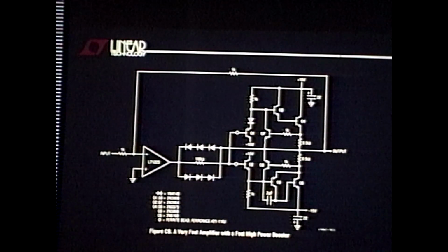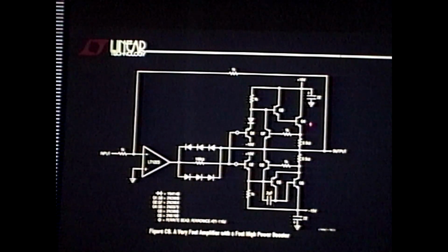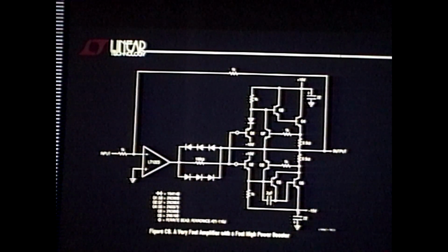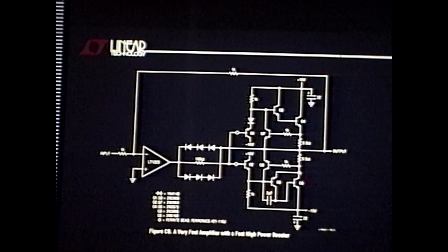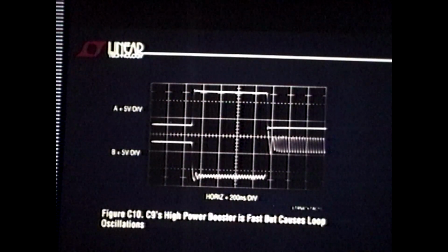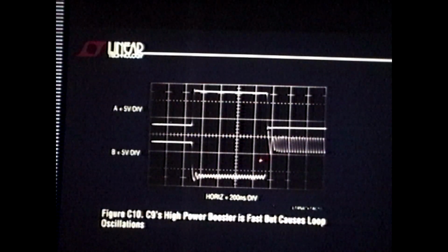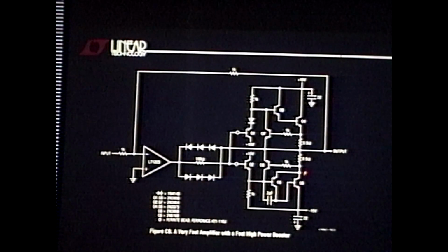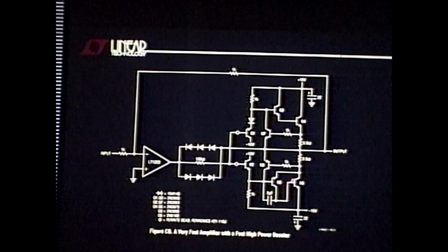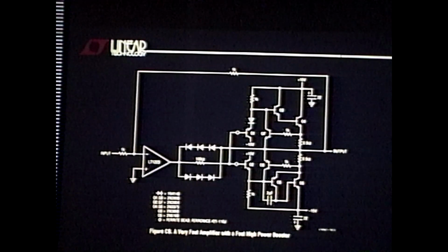The other thing you'll notice is, remember I said when I described this circuit, you had asymmetric bandwidth in this thing, gain bandwidth. You've got just current gain through here, followers. You've got voltage gain with this fast quasi-connection here. You notice that the amplitude and frequency of oscillation are different for positive and negative sides. That reflects the fact that you've got asymmetric gain bandwidth in this thing with this quasi down here.